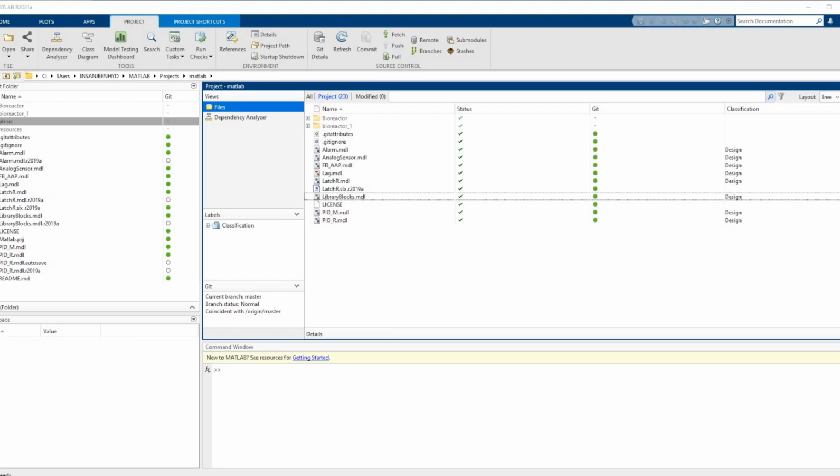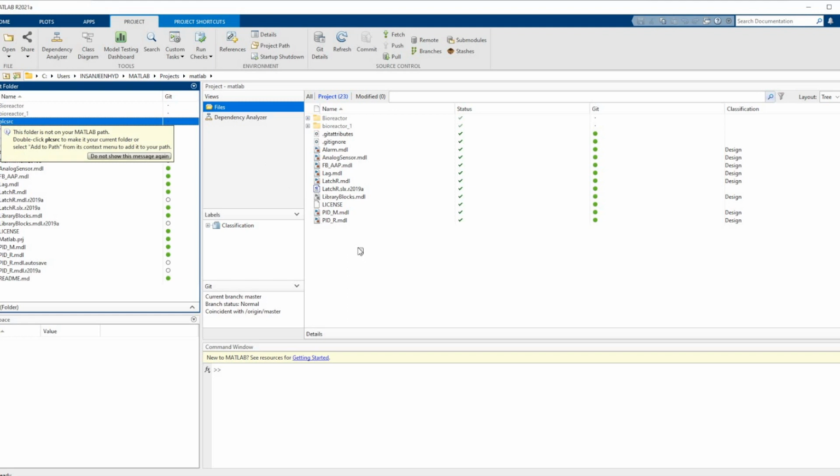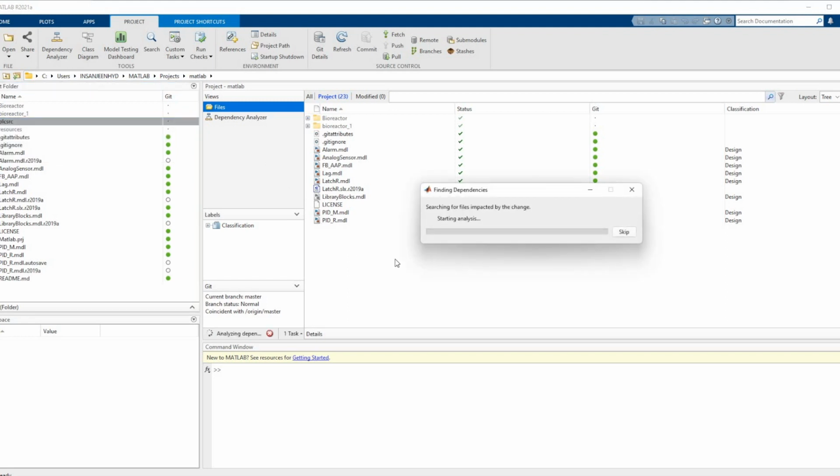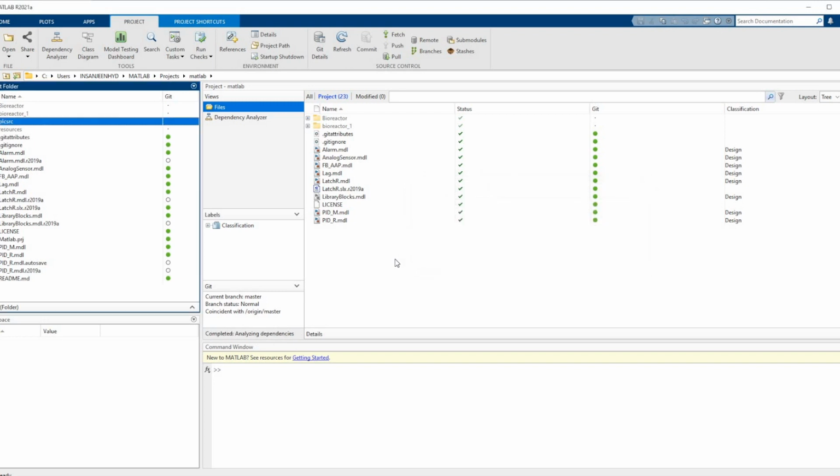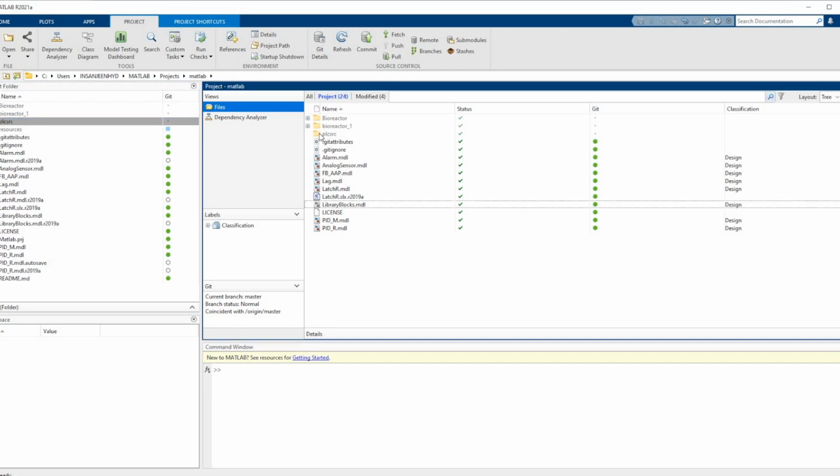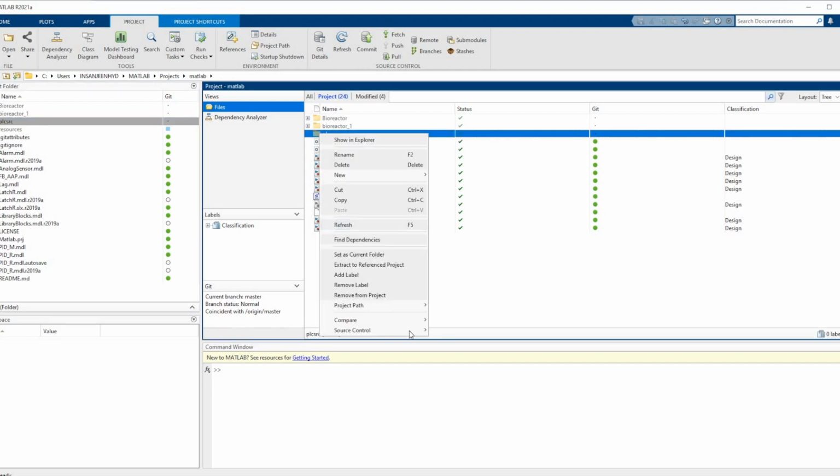So now we have developed code and targeted different IDEs, but how to do the version control? Simulink also supports version control. You can connect it directly with Git, or with SVN. Two options are there, which I have checked, and I will show you how we can connect it with Git and get version control.